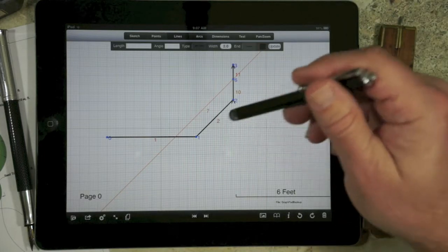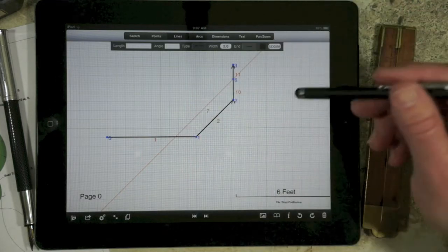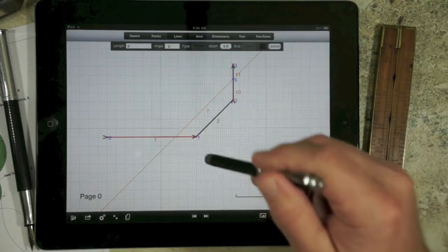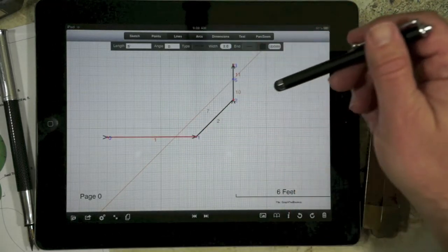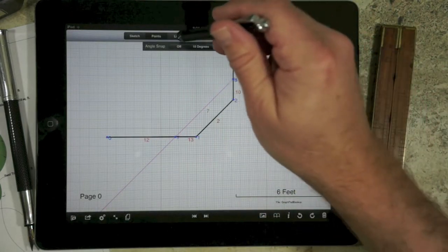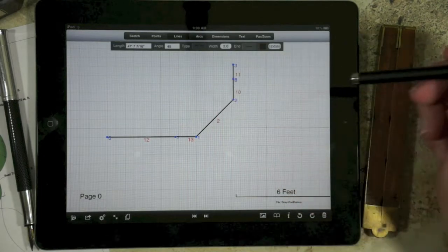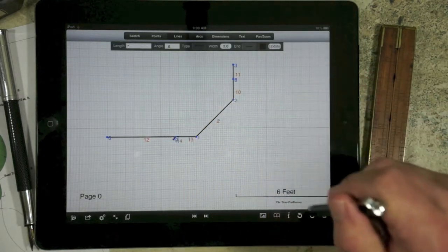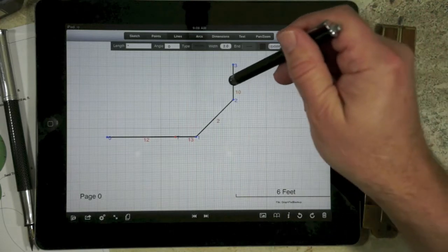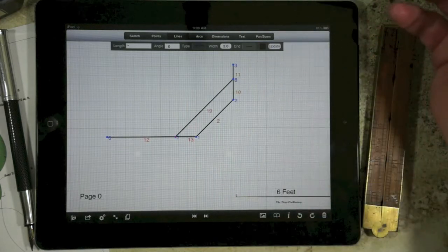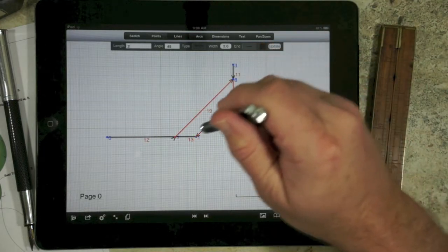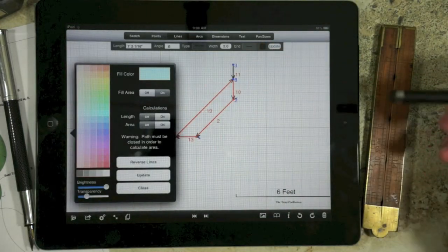So to fill out this geometry, all we would have to do is to, in lines mode, select line 1, we have line 7 selected still, hit points, it broke that line, and now go back to lines mode, delete this one line, select point 7, notice I wasn't quite close enough, select point 7 which is highlighted, select point 8, and it creates line 19, and now we can select the lines around our perimeter.